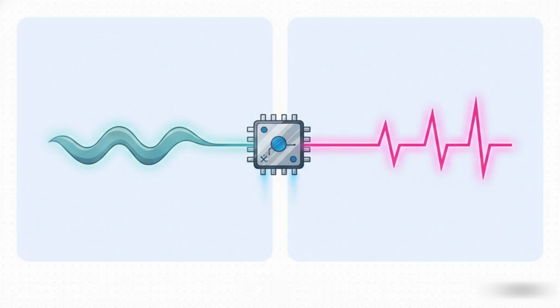The idea behind PWM is both simple and totally brilliant. We start with two signals. The first is our reference wave. This is a perfect, low-frequency sine wave, and it's the beautiful output we're trying to create. The second signal is our carrier wave. This is a high-frequency triangle wave, and it's going to be the tool we use to build our reference. Then, we just continuously compare the two.